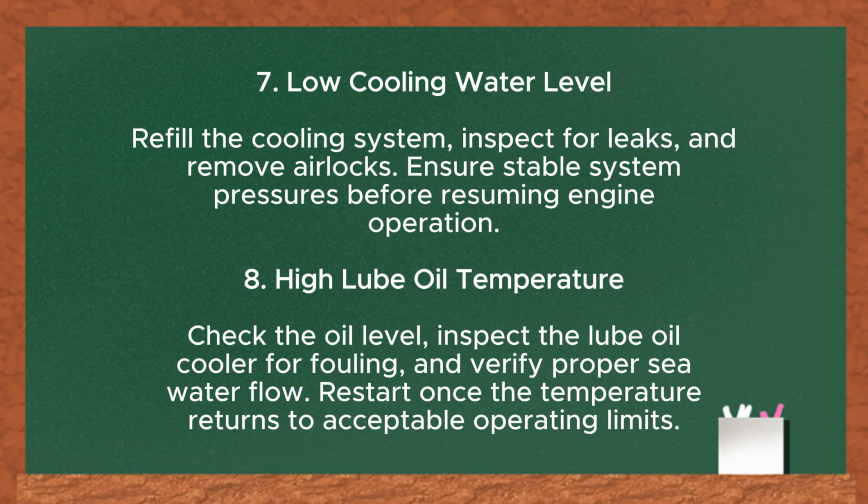And the 7th, low cooling water level. Refill the cooling system, inspect for leaks, and remove airlocks. Ensure stable system pressures before resuming engine operation.